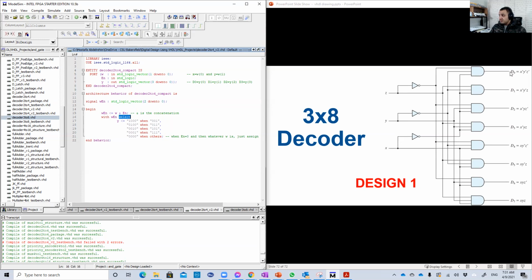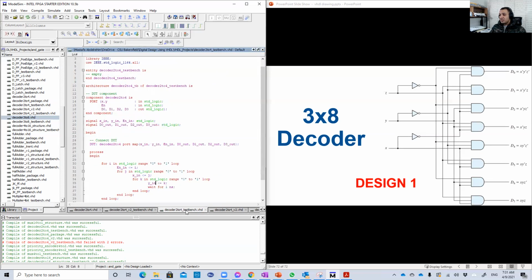For example, let's call the outputs one variable, 8 bits from 7 down to 0. So the output y will be equal to 1 0 0 0, then another 4 zeros, when the inputs are 0 0 0, and so on. That would be the idea if you want to implement the same circuit using the with select when statement. So let's go back to our circuit.